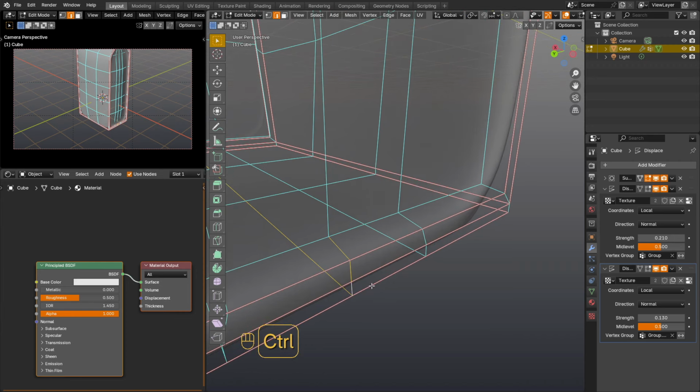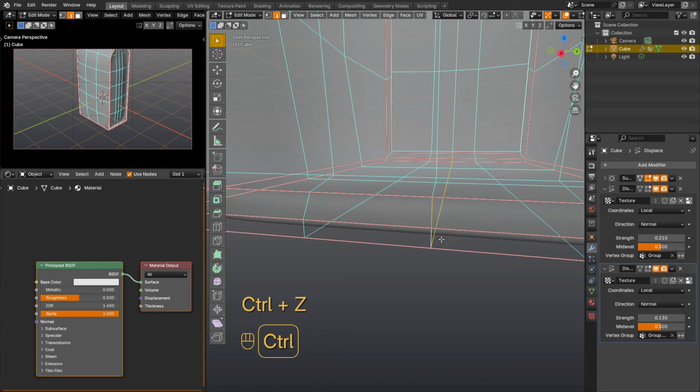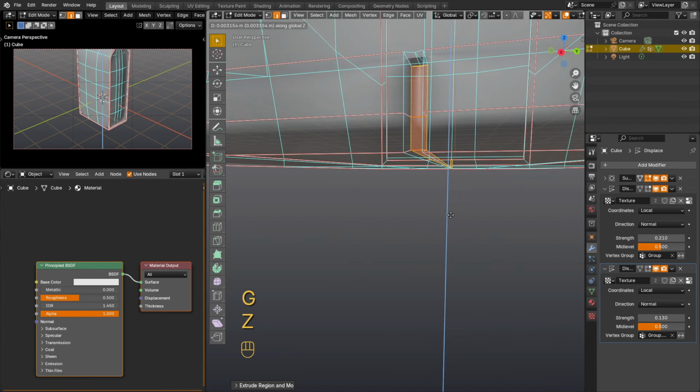And now you can press the E and S combination to push these faces inward. You just need to correct this effect a little, you need to cancel the selection on the vertical faces and slightly raise the horizontal ones along the Z-axis.